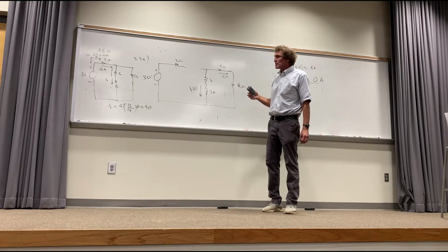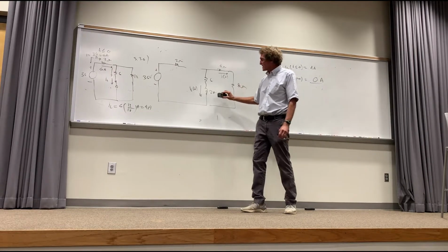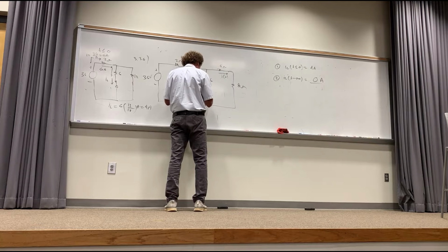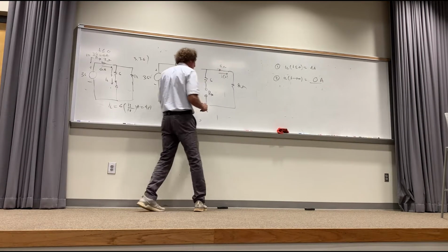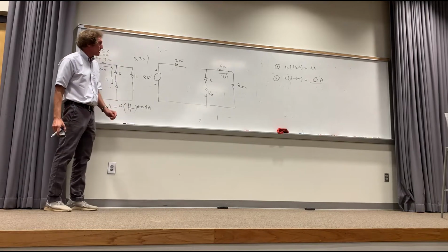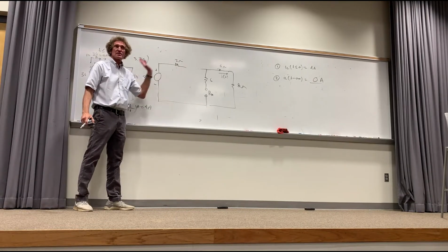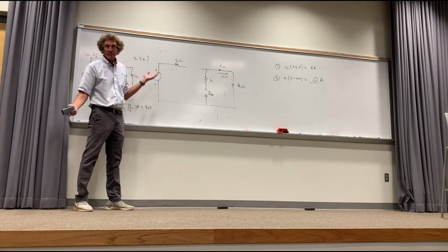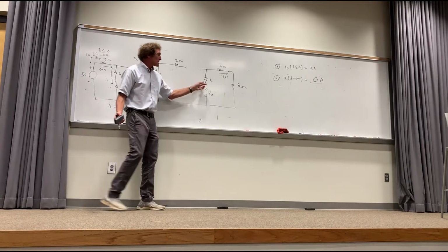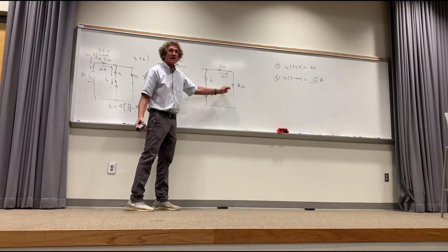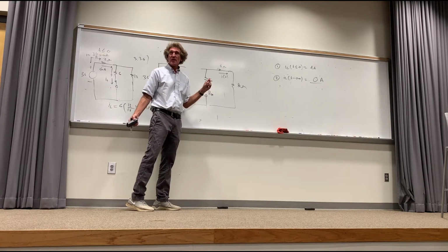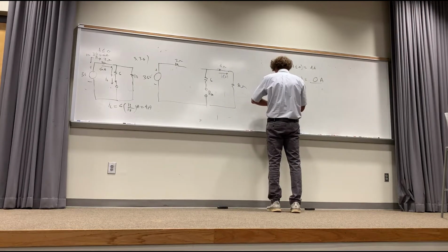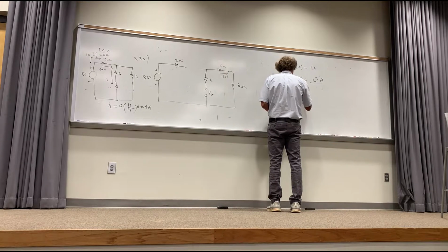Now, the next thing I do is I want the resistance, Thevenin equivalent resistance. So I'm going to erase this right here, and I want the resistance between these dangling ends. Correct? Now, please watch this. This part of the circuit has no effect. It's been taken out because it's open. That circuit's open, right? How much resistance is across that? Well, it would be 6 and 4 is 10, right? And 10 and 8, 18 ohms. Do you all see this? How many do? 18 ohms, right? Sure. So R Thevenin is 18 ohms.